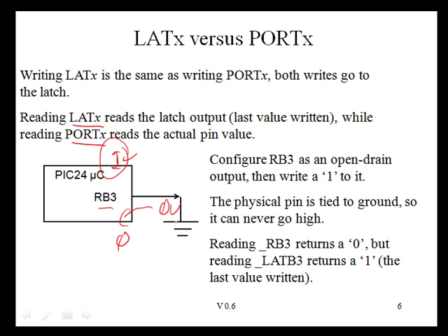By the way, if you ever short an external pin to ground like this, never configure this pin as an output and then try and drive it high. If you configure this pin as an output and try and drive it high, you can draw an excessive amount of current through the port and can damage that port pin.